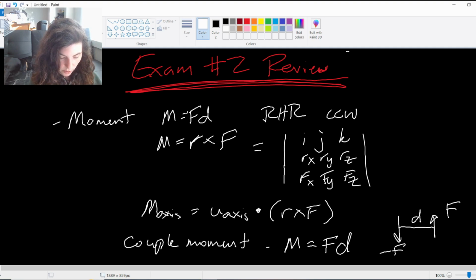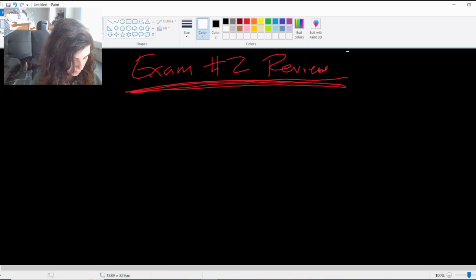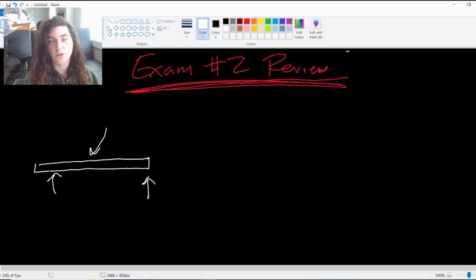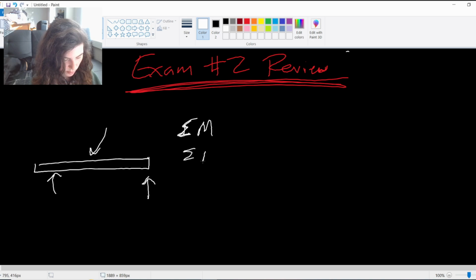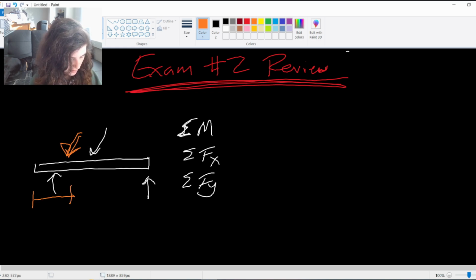I'll also ask you about equivalent forces. So these were when we had a system on a body or something and we said, all right, find the equivalent force using the sum of your moment equation, sum of your x and sum of your y forces, and then being able to find the position of that resultant force. So when you're finding that position of the resultant force, say it's here, for example, how do you find this distance d?